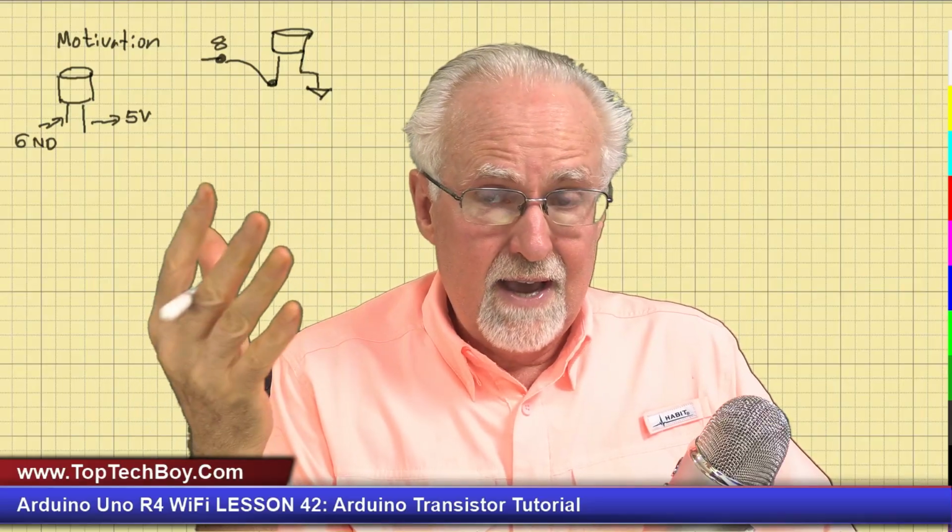Now that's kind of a straightforward way to think about it, but what you're going to see is if you did that, you would likely burn out your GPIO pin 8, and you would possibly even burn out your whole Arduino. So why is that? Well, let's look a little bit more at this buzzer.